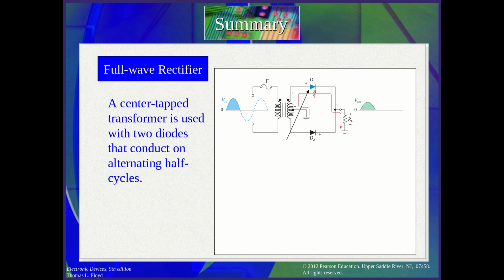So this device, diode D1, will conduct, and all of the half cycle will go to the load. However, the other one, if it goes like this, will be minus, so it will not conduct. So in the first positive half cycle, D1 will conduct and the current will flow through D1. However, D2 will be in reverse bias.